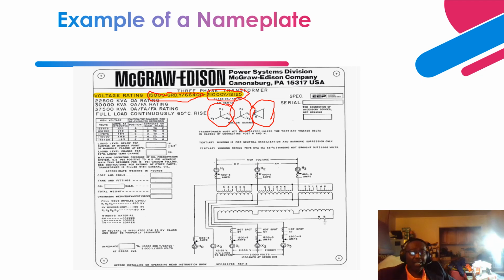It is usually the corner of it that is grounded. Okay, so the goal is to basically stabilize the overvoltages that can occur due to the stray capacitance from this because it has a high impedance, right? So the corner of it is grounded so that it prevents overvoltages that can basically destroy the insulation that is wound on the winding.